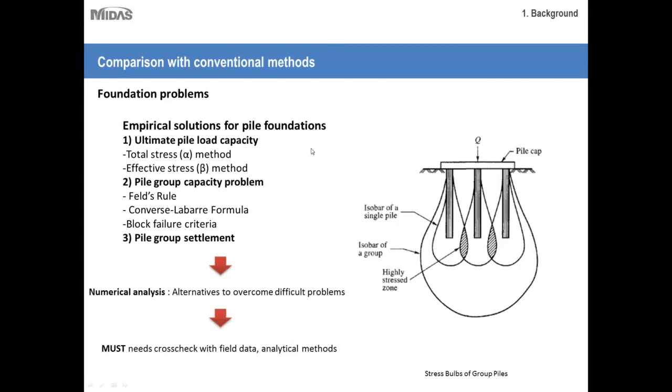So this is a very reliable way of doing the analysis for foundations, but unfortunately it's very costly and time-consuming. As you can imagine, it takes quite a bit of time to take all the materials out there. It also takes time to run the tests. So in order to circumvent this process, various theoretical methods have been developed to make it easier for engineers to do their pile foundation designs, especially for group pile foundations.